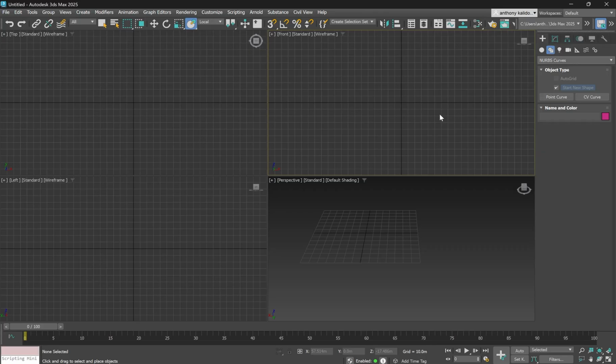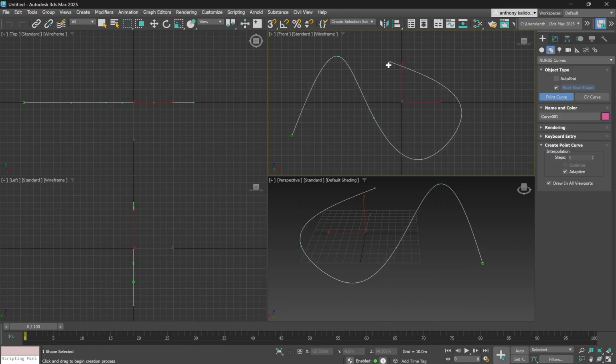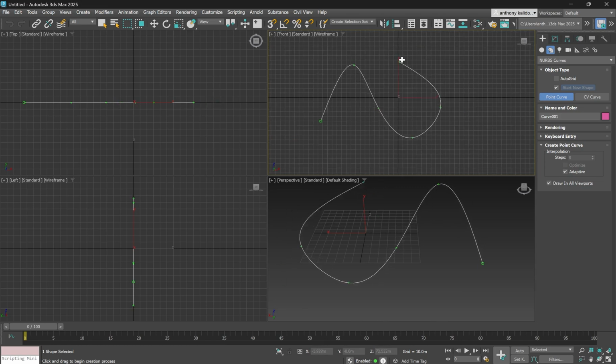So, click Point Curve to create one. That can be located right here. And start clicking to add NURBS control points. As you move your mouse, notice how the curve shapes change several vertices away? Well, that's how NURBS behave, affecting larger portions of the curve at once. See, this can make them harder to control in media work especially, which is why Bezier splines are usually preferred for local precision. You can see, even as I start moving, it affects that entire spline.